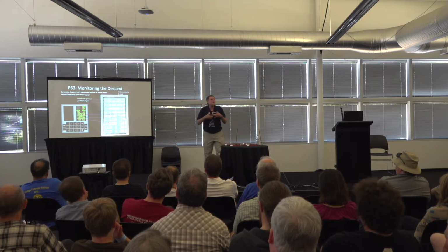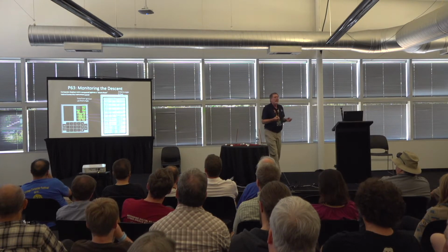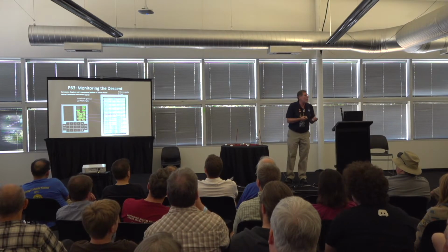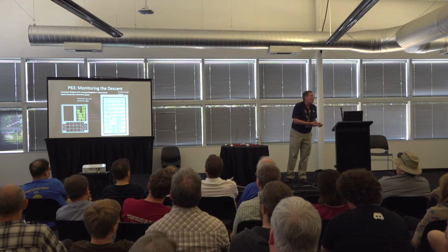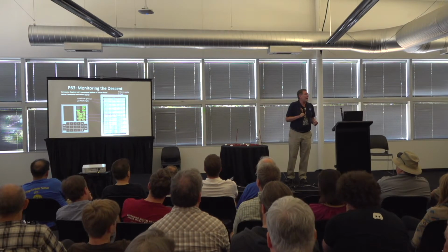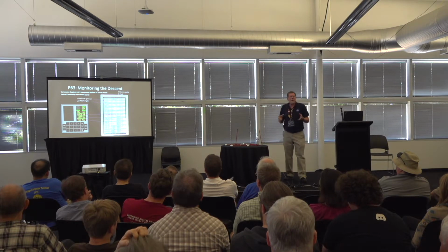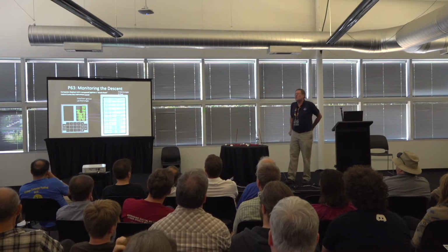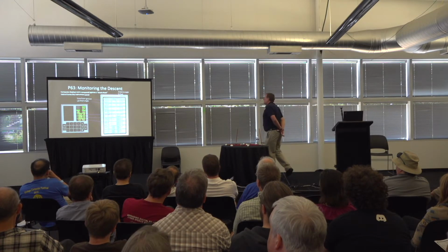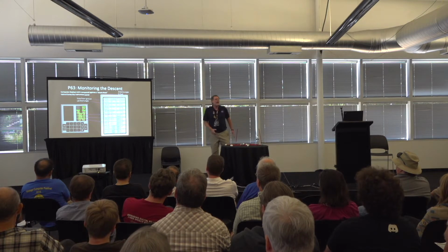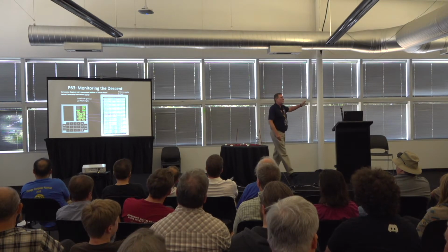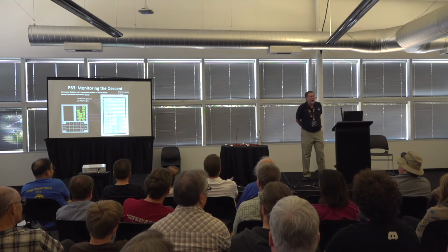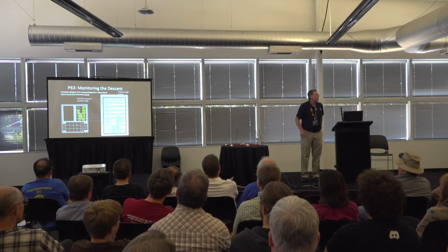And it's brilliant. The things that you're really interested in is, is my altitude okay? Am I going down at the appropriate speed? Not too fast, not too slow. Am I pitched over at the right attitude? All these are important questions. And yeah, it's an index card that is Velcroed to the instrument panel. It is no more complex or simple than that. What are the antenna angles? Remember, Apollo 11 had communications problems that they were surprised to get? Well, if they have it, at least they have a cross-check of where that antenna is supposed to be pointing.